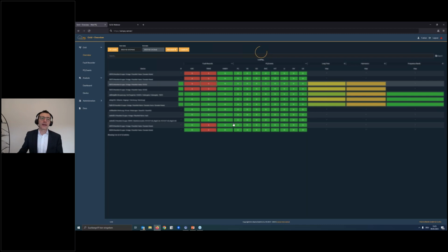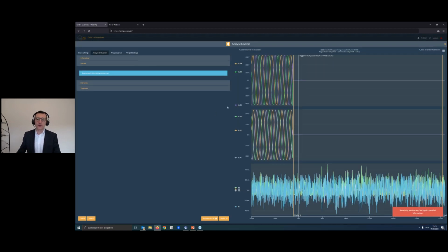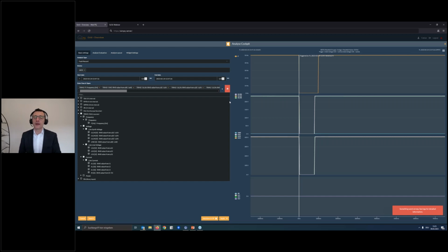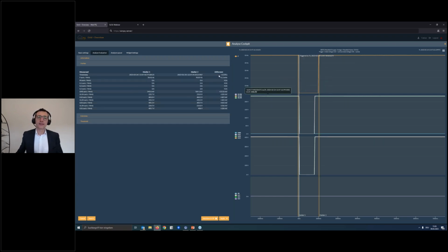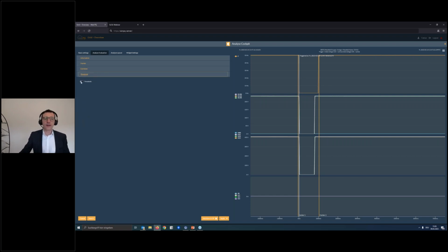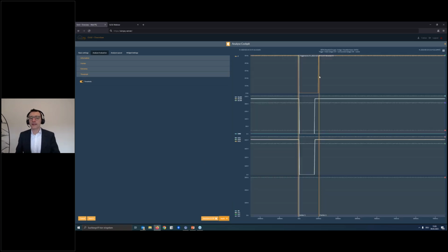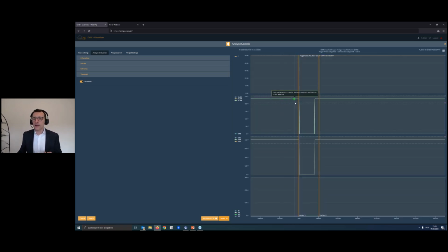If you click another part of the software, another true RMS recorder, maybe there is another outage which is displayed a little bit differently, and there we can make it as an example. Just click here and click here, and we can see maybe this outage was approximately 1 second. If you want to see the threshold levels, just click in the field of thresholds, and the thresholds are applied to the analysis that you can see here.